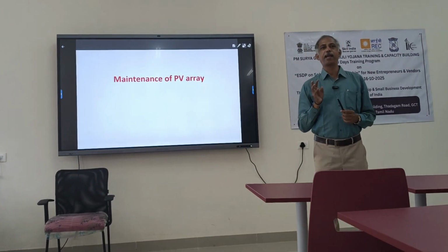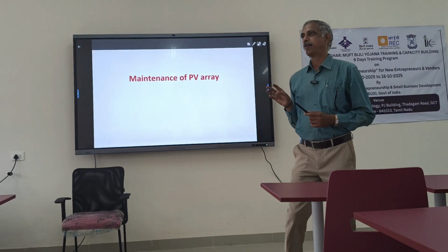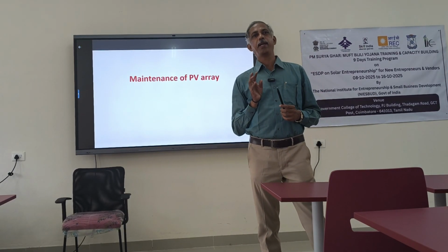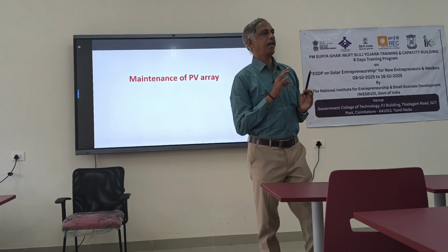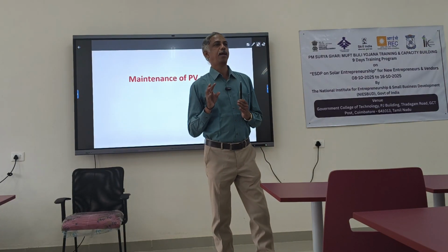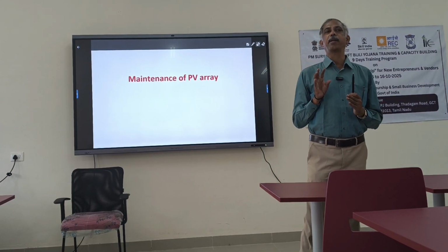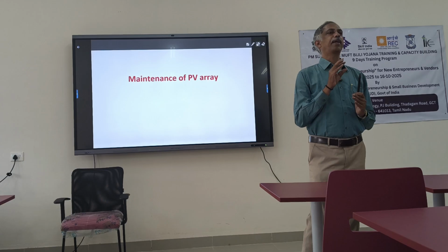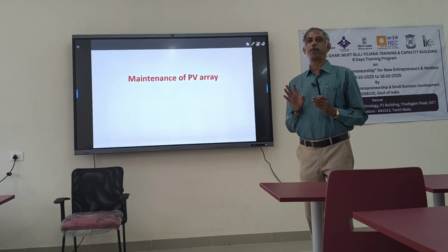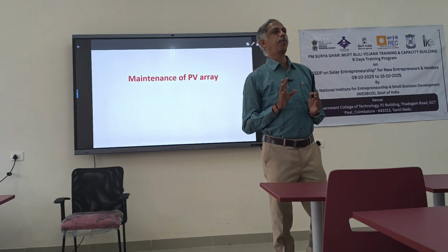So what is the need for operating the solar system at the maximum power point? Because the panel should not be underutilized. At any irradiation level, it should produce its maximum power. You have to identify that operating point and operate the solar panel at that point, then you can get the maximum power from the given irradiation. That is the concept. For that we have a DC-DC converter, a power electronic circuit, which is used to harvest the maximum power from the solar system.